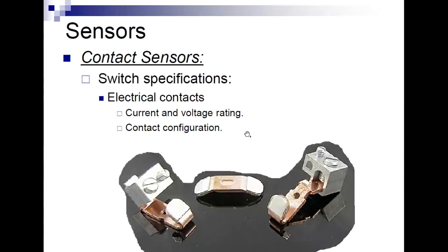Okay. All right, so this here is just showing the contacts for the sensors. These are really heavy duty commercial type contacts. As I mentioned before, they have both a current and a voltage range on them. So you also have to be concerned with how much current and how much voltage you're working with on these to make sure that they don't wear out or burn out after 2 or 3 uses.